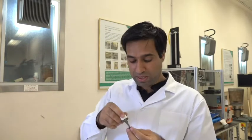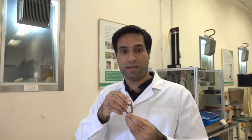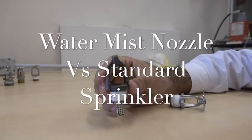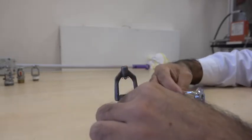This droplet size is because of the exceptional properties of water. Because of evaporation, it can cool the temperature inside the compartment, as well as suppress the fire. So this is the water mist nozzle, and I want you to compare it with the standard sprinklers.